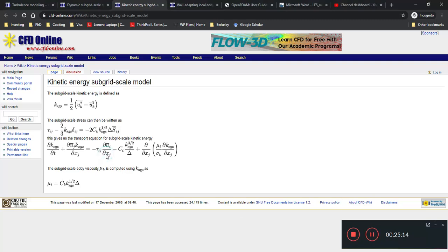That means the turbulent kinetic energy has to dissipate somehow into heat or what have you. And this one also is a dissipation term, viscous dissipation or subgrid dissipation. So there are two mechanisms at play probably, the viscosity as well as the subgrid viscosity. Both of them contribute to this dissipation of kinetic energy.